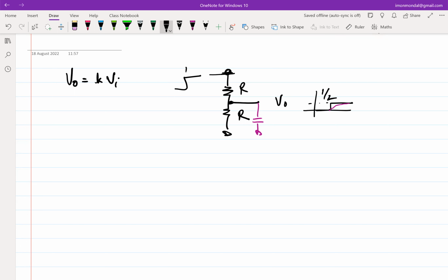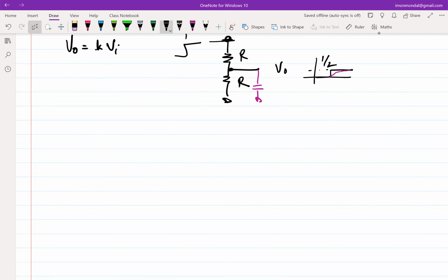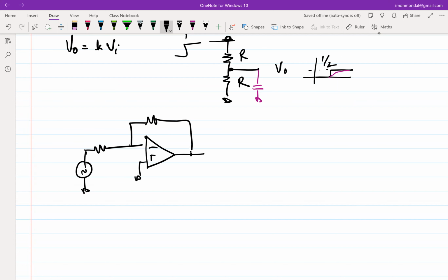Even if I take you back to the ideal op-amp circuits, where you assume the op-amp is ideal and so on and so forth, you apply an input here, and the output appears directly here immediately, right? This type of modeling is good as long as you are not particularly interested in how the output is settling, but you are only interested in steady state. But as we will soon see, that is not good enough, because ultimately you will not design a circuit and wait for one day for the output to settle, right? You would want your phones and computers to be as fast as possible.